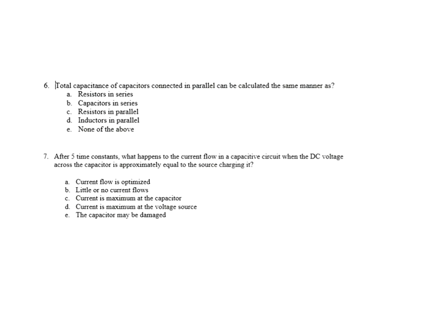All right, total capacitance of capacitors connected in parallel can be calculated the same manner as, well, caps in parallel, I add them together. What other component can I add together? What other component in what kind of circuit would be series or parallel? Well, capacitors in series, no, that's reciprocal. Resistors in parallel, no, that's reciprocal. Inductors in parallel, yeah, that's reciprocal. So the only one here is resistors in series are added together. So resistors in series, you add them together, that's how you do the same thing as caps in parallel.